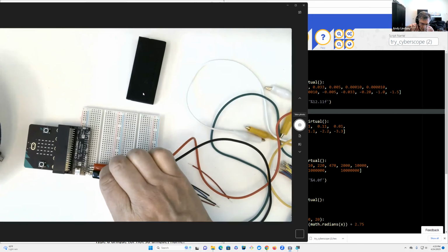What you can do is take a jumper wire and jumper up to something empty up here, and then put the 3-pin header in there too. Sorry, go ahead. I just thought there's something special about P2. Well, there is, which is why you would be jumpering if you wanted to keep it convenient to follow the tutorials, so you don't have to change the code every time.